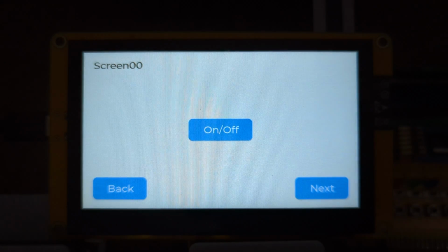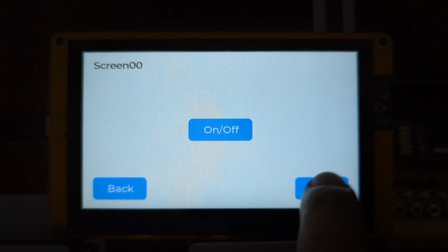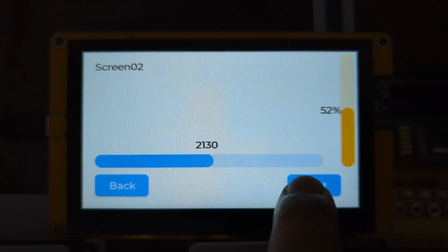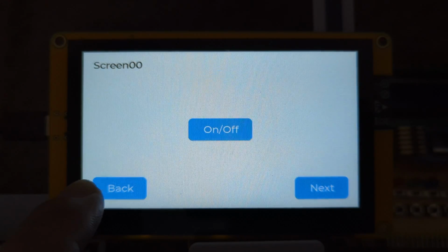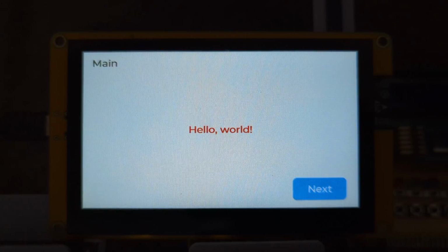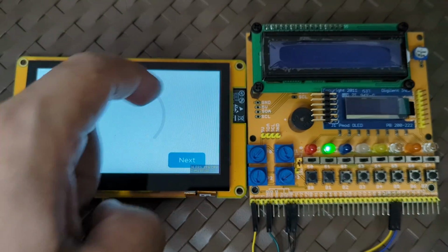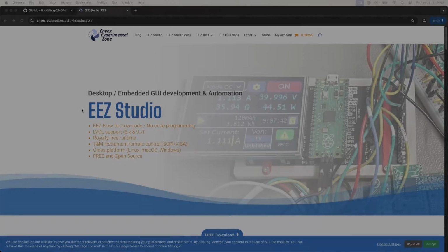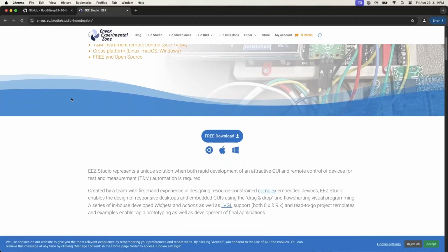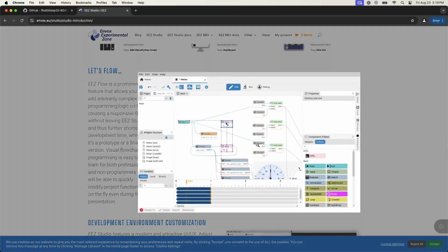By the end of this tutorial, you'll have built an application featuring multiple screens and a variety of interactive widgets, including buttons, bars, arcs, labels, a text area, and a keyboard. These widgets will interact with the serial port and control external components like LEDs, a buzzer, and a potentiometer. To design and lay out the screens and widgets quickly, we'll use EEZ Studio, an open-source design tool that generates LVGL-compatible code.